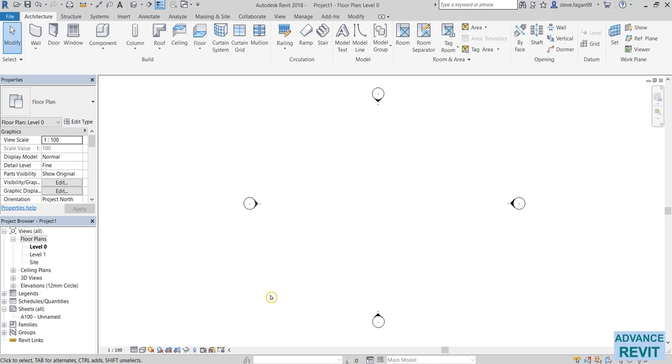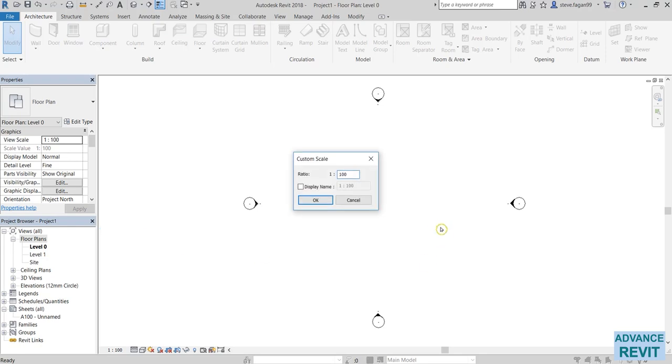Again, if you're familiar with AutoCAD, so in your model space, you'll have a scale of 1:1, and then in your paper space, that's where you'll create your viewports and then scale on your sheet. So with Revit, what you do is you apply all of your visualizations and scalings, etc., to that specific view. So it's currently set to 1:100. If you select it, you'll see our typical list of scales. If what you want isn't there, again, just selecting custom, we can create a new scale.